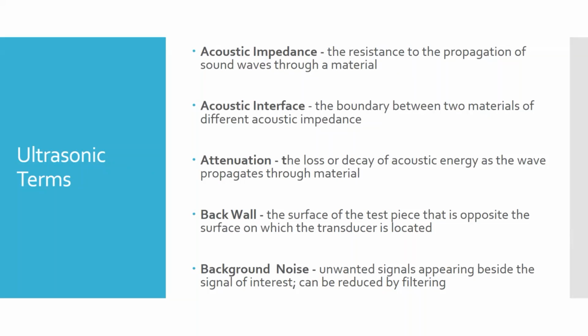For our environment, you don't have to worry about it. It doesn't have to be a super quiet room. If you're doing ultrasound, people can talk, people can be moving around. What you do have to be aware of is if you're working on equipment that's energized, things like motors that are running. There may be some high frequency vibrations coming out of a motor that's spinning really fast. A motor that's spinning at thousands of RPM is going to have a several thousand hertz frequency coming off of it. You hear that sound.